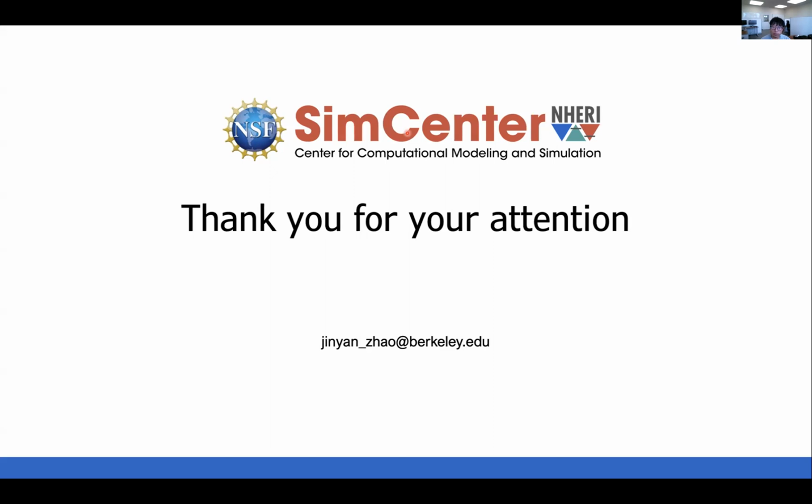Oh, I see. So the economic loss is included in Pelican. The Pelican fragility curves I showed you were based on intensity measure. I have the damage state, but Pelican also has such information for the replacement cost given the damage state of the building. So by conditioning on the damage state you calculated from all the analysis, Pelican will give you how much money you need to spend to repair your building stock. And also Pelican can suggest perhaps the building has collapsed completely. There's no chance to repair it. You can only replace the building.